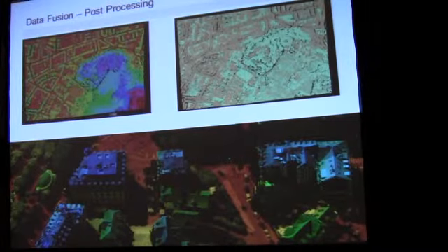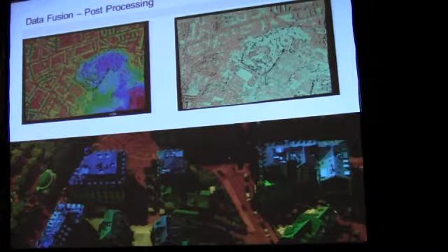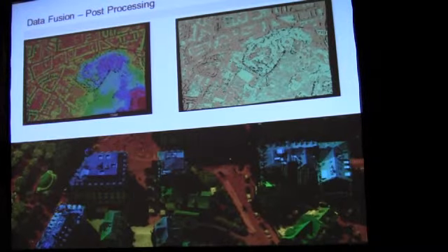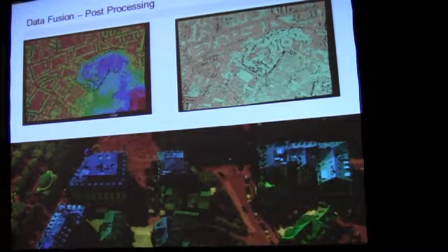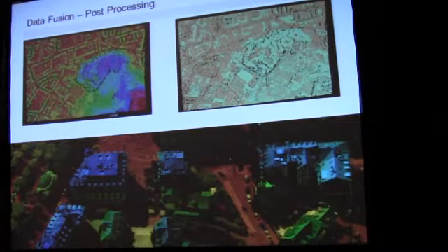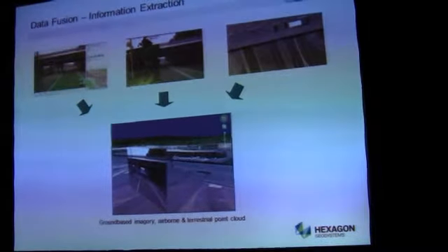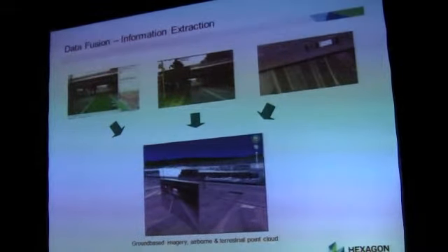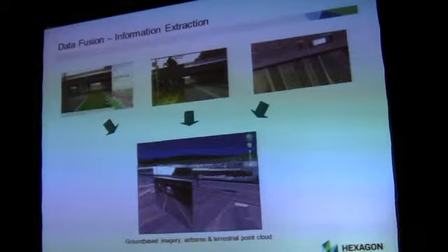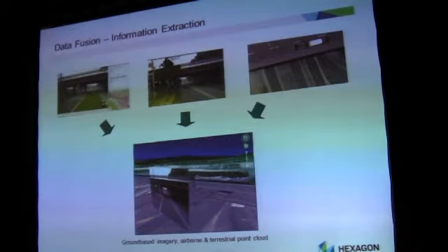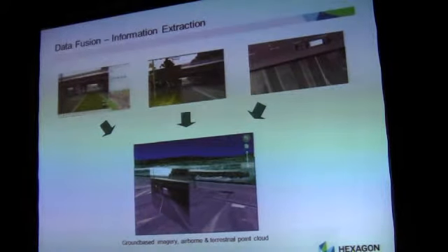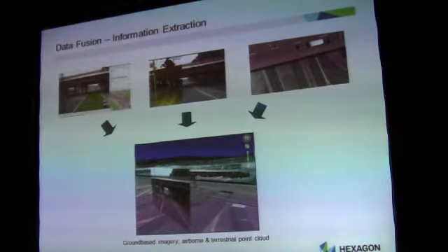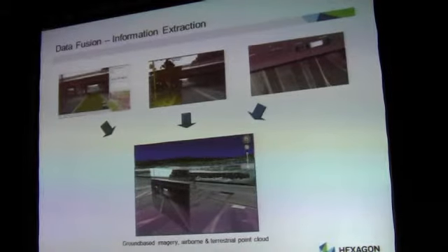Now, of course, you want to bring that together with LiDAR and image data. The first challenge is, which point do you choose? Which point do you select? And that's becoming very, very difficult. We've done one example here with a Swiss university, bringing together terrestrial data, mobile data from a mobile vision system, with the RCD30 airborne data. We created point clouds. What do you think the first hurdle we came across was? The data sets didn't match by 2 meters. Why? Different coordinate systems,